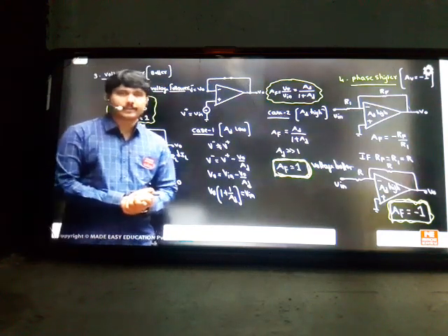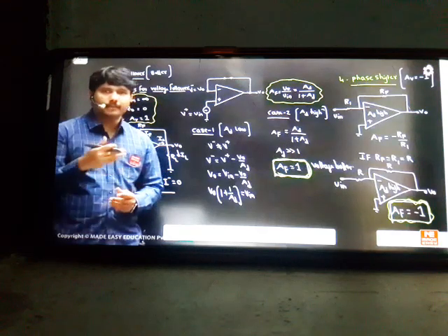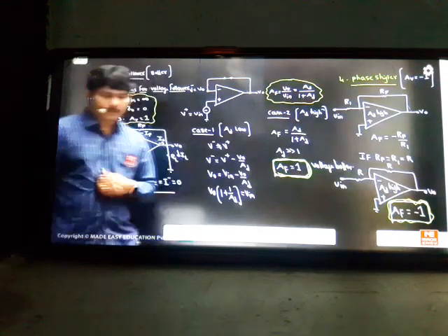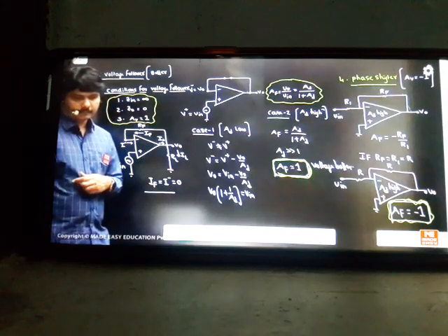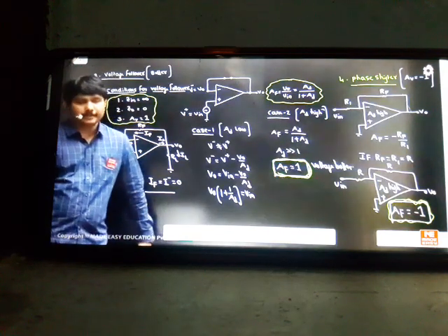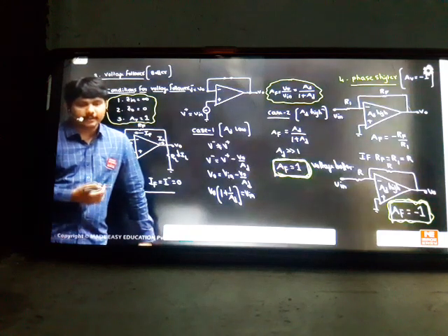Yes, Vidyadas, I think you understood what I said. The terminal should not be left open like that. We should give some input to it. Otherwise, if you don't give any input, we have to ground it. Unnecessary noise will trigger your op-amps and give unnecessary outputs. So this completes the 4 amplifiers in our class. Hardly 4 more topics are there to cover the amplifier designs.